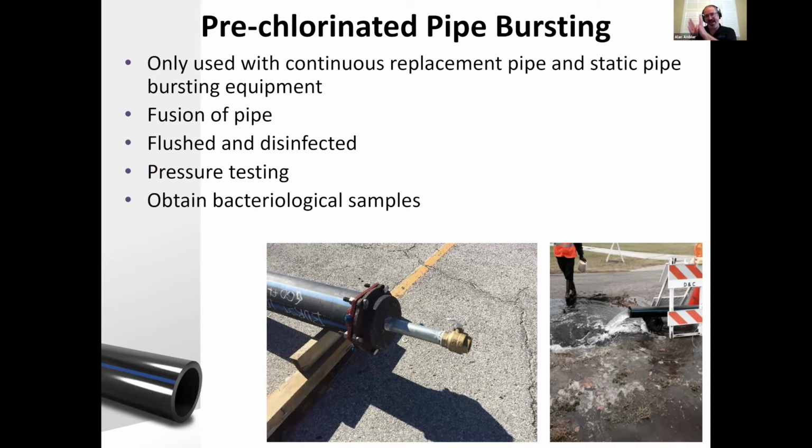So the end of the pipe, after you've drained it, is often sealed to a swivel or an expander head that goes right on top of the high density polyethylene. Then you can pull it into place, make those service reconnections, and then flush that pipe out and plug it right back into service. So it is approved in many states throughout the United States as an easy way to take limited outage periods. So all this task can be accomplished from about 8:30 to 3:30 p.m.